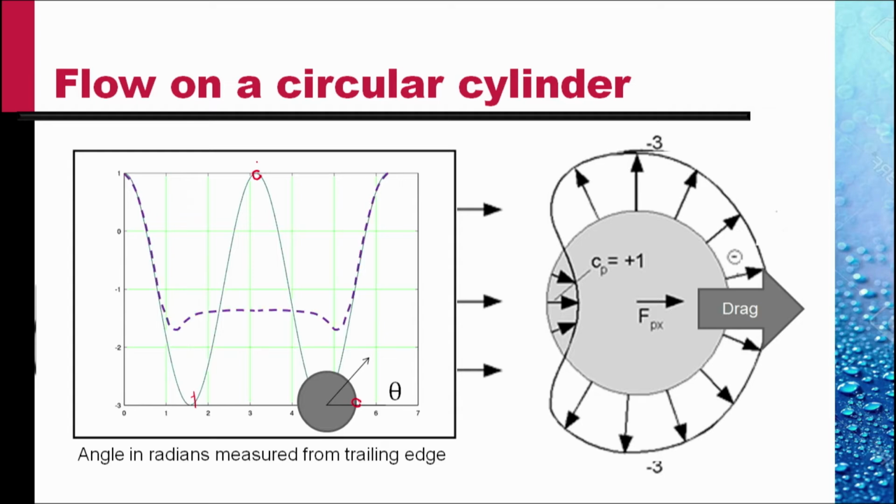So pressure in the wake has not recovered to the value in front of the cylinder, and this results in considerable drag. Since this drag force is because of pressure forces, when the drag coefficient is normalized with respect to pressure forces, we get a value of the order 1.